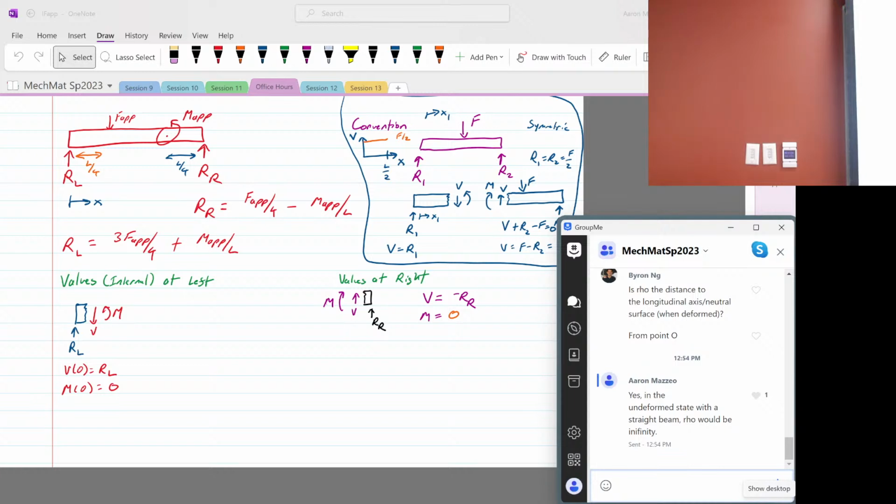So what do you go into your EV model? No, that's supposed to be Young's modulus, it's less than 1. That's the issue. That should be 210 for the 200 GPa. You can just type in GPa and it'll probably work. Okay. All right. Okay. Yes. Okay.